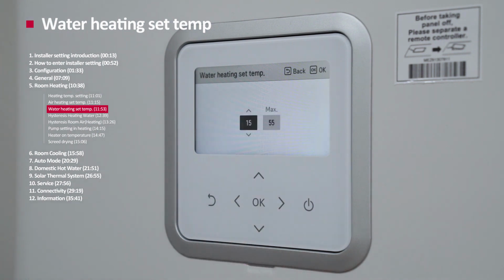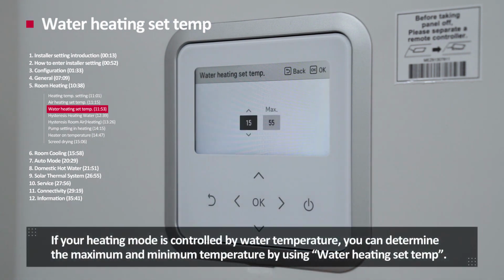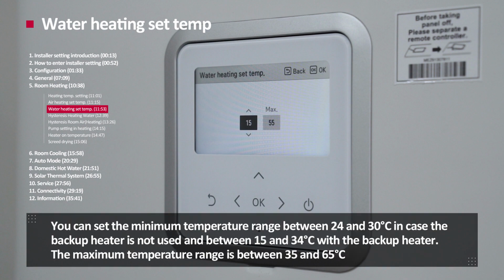Water heating set temperature. If your heating mode is controlled by water temperature, you can determine the maximum and minimum temperature by using water heating set temperature. You can set the minimum temperature range between 24 and 30 degrees Celsius in case the backup heater is not used, and between 15 and 34 degrees Celsius with the backup heater.